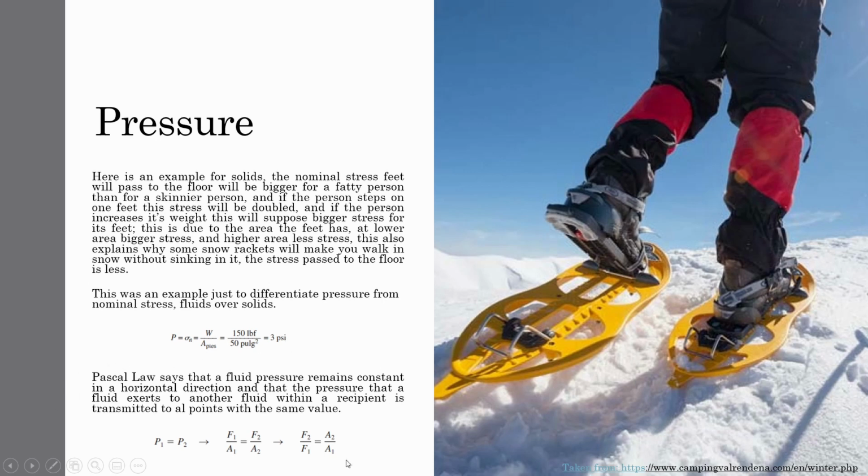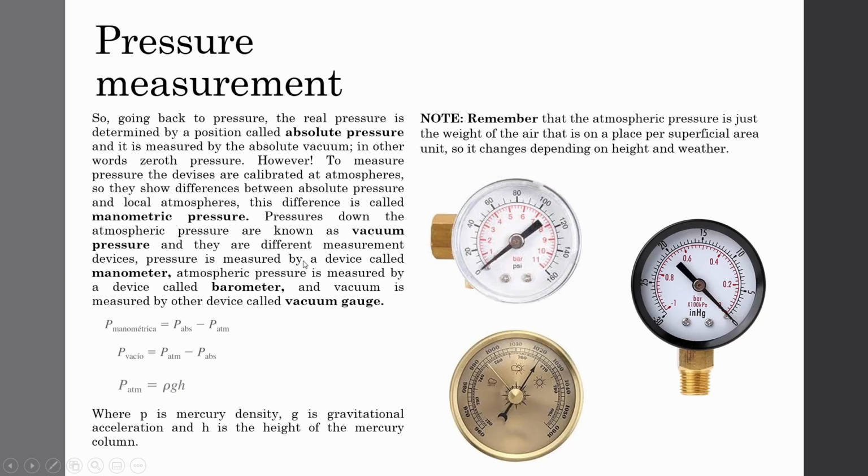Okay, and we have another concept that is introduced in pneumatics, but I will state it here because it is important. It is Pascal's Law, and it says that fluid pressure remains constant in a horizontal direction, and that the pressure that a fluid exerts within a container is transmitted to all points. So this is the hydraulic press example where you lift a car with Pascal's Law. If we increase the diameter on one side of the piston and decrease it on the other, we'll get a lot of pressure transmitted to the other side. But that's another topic for pneumatics.